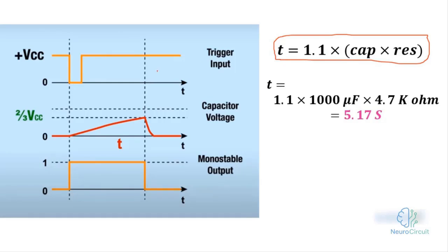Look at the diagram on the left. I have VCC, and I have the trigger input, meaning I have the input for pin 2, which you can see here is in the low state in this section and in the high state in this section. So in this part, it shows us a time interval for the capacitor to recharge again. That is, this interval that exists here, and is between the two dashed vertical lines, is what we want to determine. This is the interval that shows us when the capacitor is going to be charged.